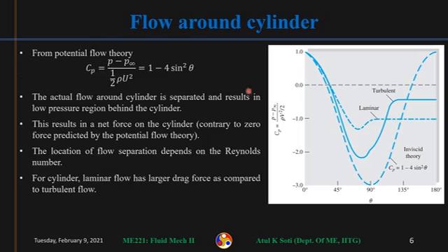Now this is why we are studying flow separation. Flow separation is very important in explaining the lift and drag forces on objects that we observe in practical conditions. So recall that when we studied flow around a cylinder using potential flow theory, we found that the pressure